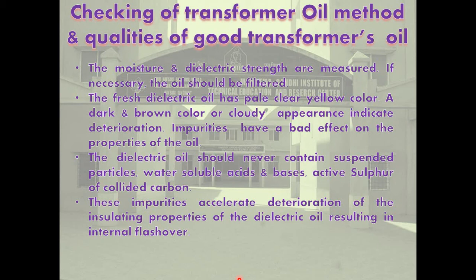Higher flash point like 145 degrees Celsius is preferred. Flash point indicates tendency to evaporate. For flash point lower than 135 degrees Celsius, the oil tends to evaporate rapidly. Thereby the viscosity rises and total volume of oil reduces.